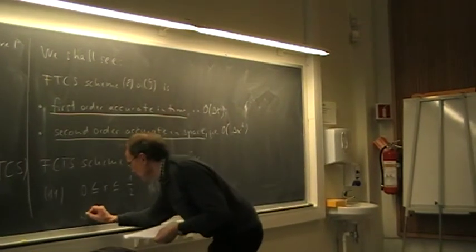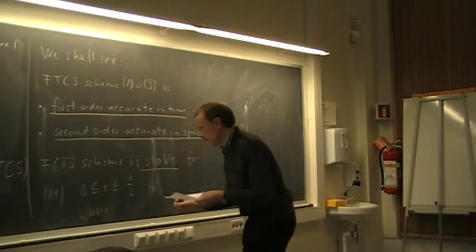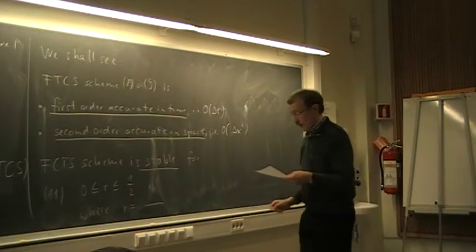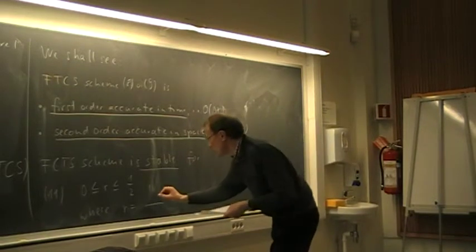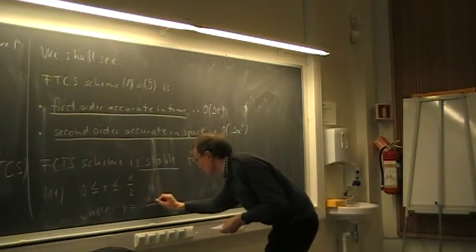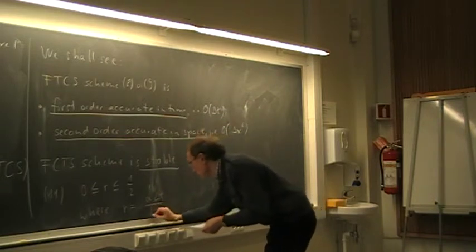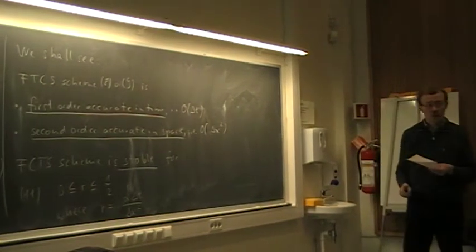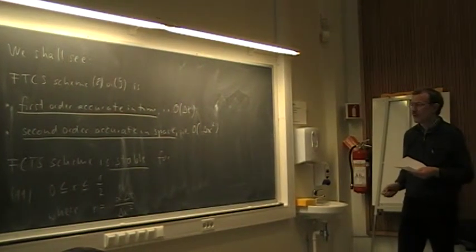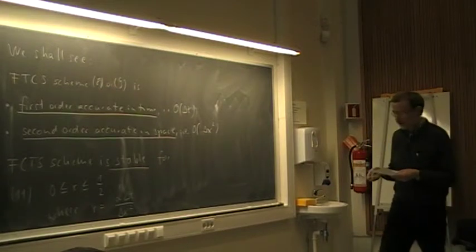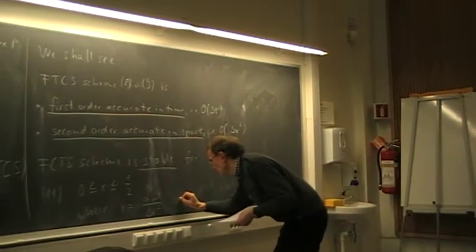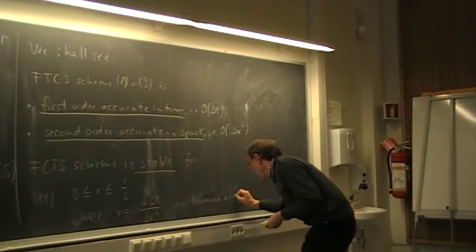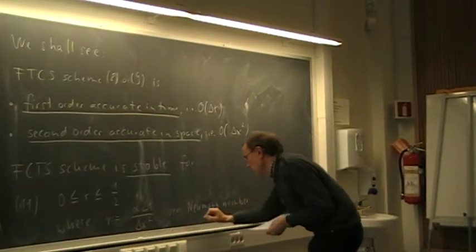This parameter, we already discussed that, is for the simplified structure. It is mu, in our case for the heat equation, alpha delta t divided by delta x squared. And sometimes I use also a name for that. I checked yesterday again in the literature. It is not so common, but I call it the von Neumann number. This is the stability parameter.